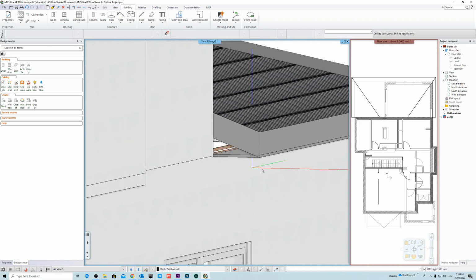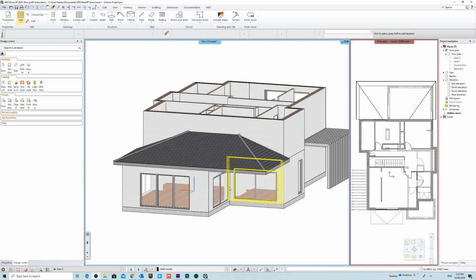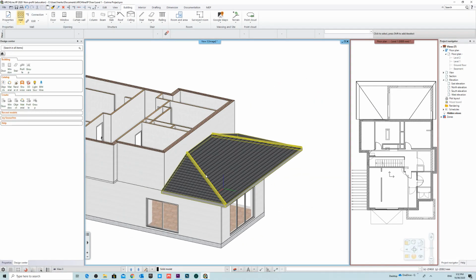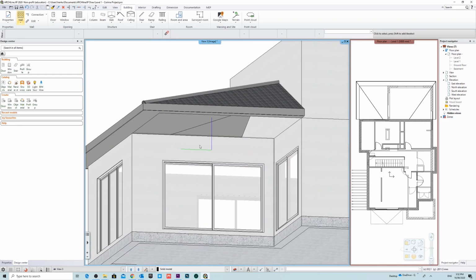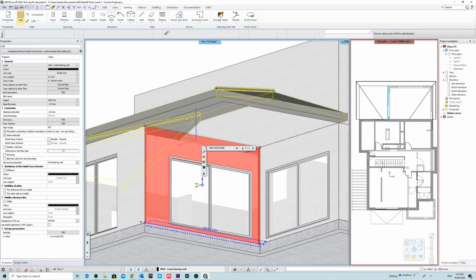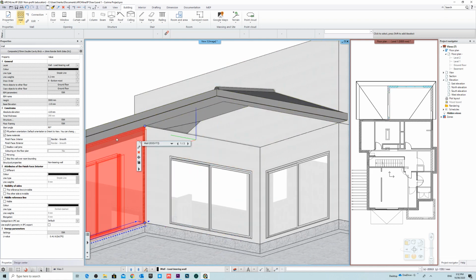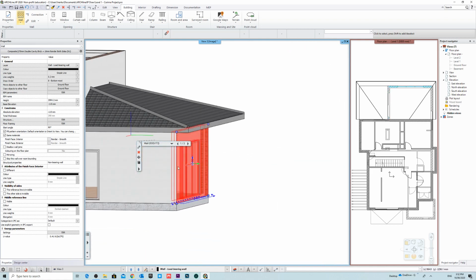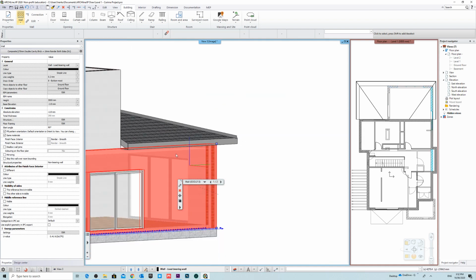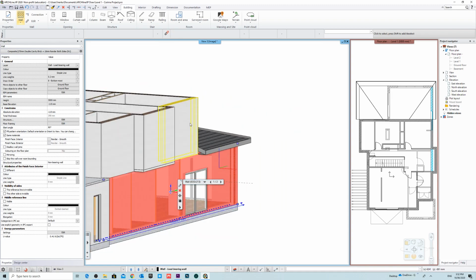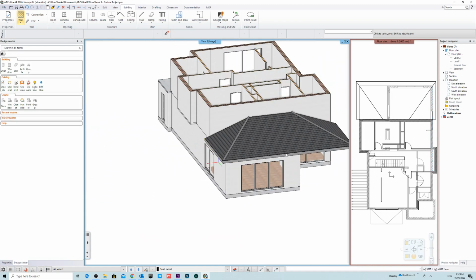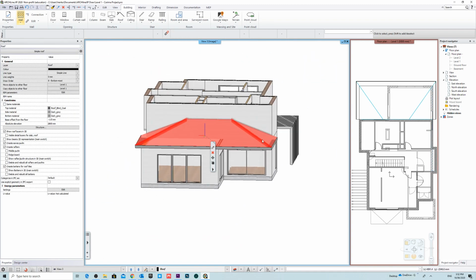So, right. So now you can see we have our roof and we have the walls. Okay. But there's one other thing we need to change. You can see this is not actually going up all the way to the roof. And what we're going to do is we're actually going to drag these walls right to the roof, and it's going to cut automatically. So we need to set that. Okay, so we're going to go onto the roof.